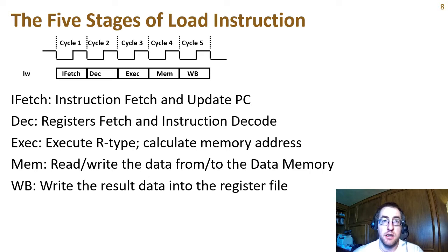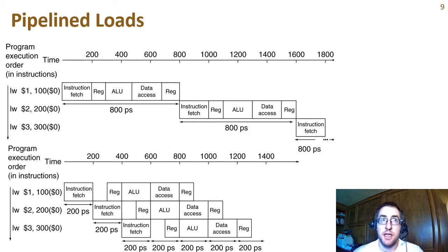The branch target address calculation is in parallel to the ALU and dominated by it. The branch also has to wait for the ALU to complete the subtraction operation for branch equal to determine if the 2 numbers are identical. The mem stage reads or writes memory, and the write back stage writes to the register file. So if we look again at our sequential timeline in the top half of this diagram, we can see that the pipelined time diagram on the bottom allows us to overlap the different stages of the instruction.